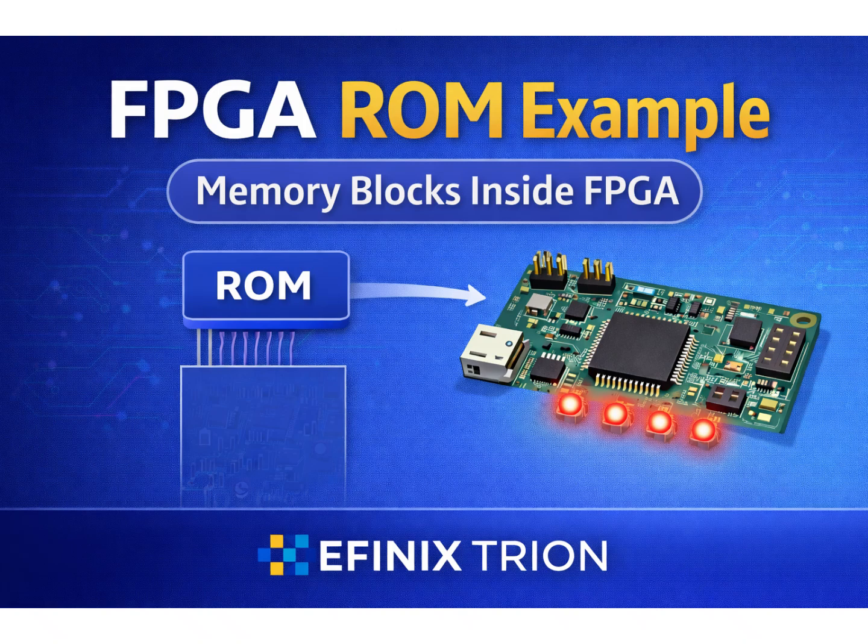In this video, we will explore how memory blocks can be used inside an FPGA to generate predefined data patterns. We'll begin by introducing a single-port ROM, where the memory contents are initialized using a hex file. Then, we'll see how a counter is used to sequence through ROM addresses, allowing different data values to appear on the FPGA output pins. Finally, we'll demonstrate the design on actual hardware, where the ROM data is observed as changing